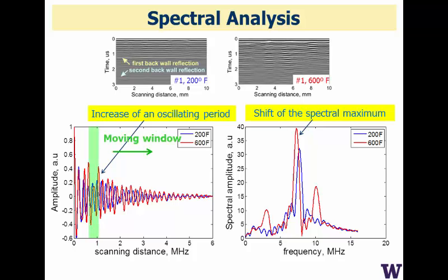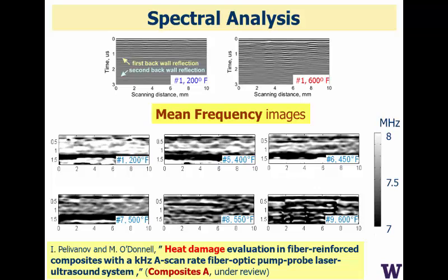Having observed that, we can come up with a very simple signal processing procedure based on autocorrelation modeling or autoregressive modeling to estimate this center frequency, that peak frequency, at every position within this image to look at the effective structure signal that is in there. When we do that, we get images like this. If you compare the mean frequency, say at the low frequency, to the high frequency, you can see that we have a much higher mean frequency as we expected.